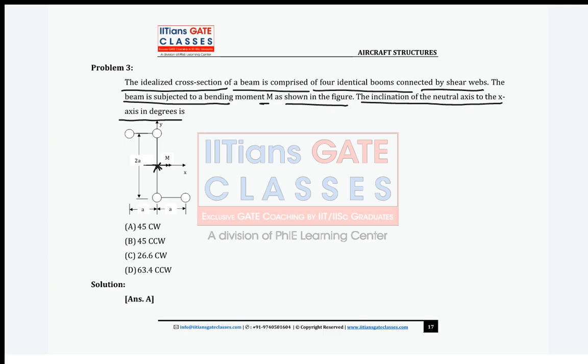So what is your neutral axis position, tan alpha? We can write tan alpha in terms of moments and inertias, right? Now in this problem, what is your Mx? It is given as M. What is your My? My is 0. Good, guys.